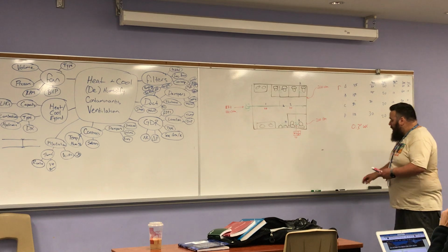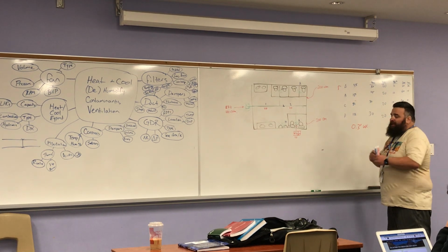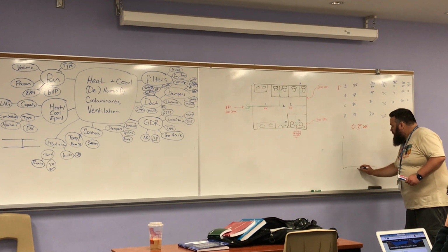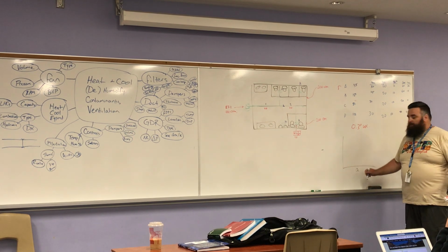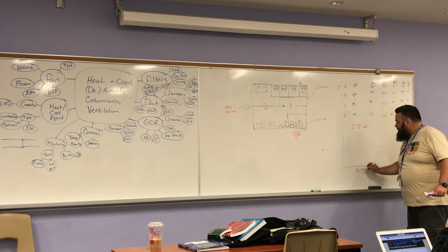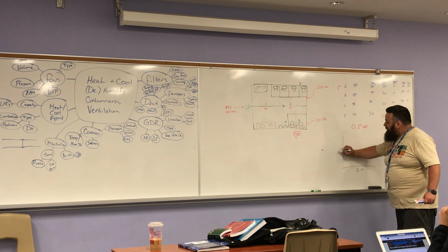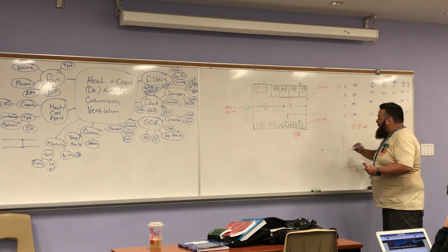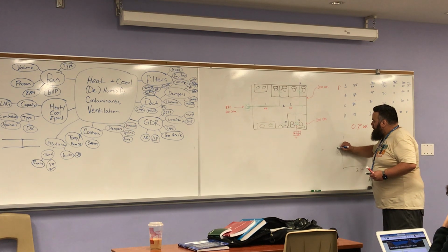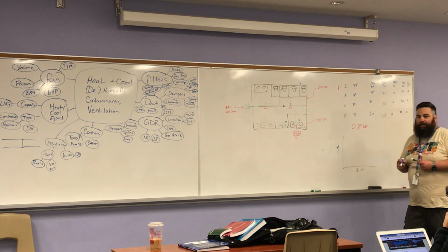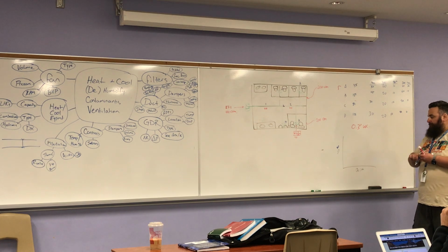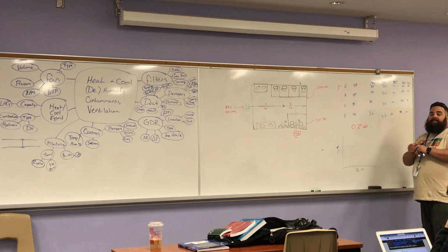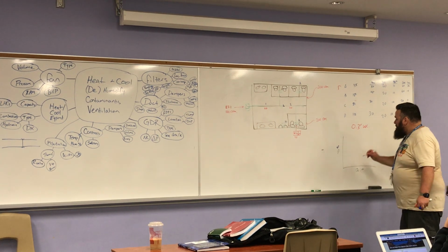So on my fan spec, and again, we'll look into the fan curves later, Q, which is flow, so CFM, and this is delta P for pressure, but I'm also going to put on the same axis in blue BHP, the brake horsepower, okay? Because that's where they typically put it on the fan, or on the curve. So, my system curve looks like this,